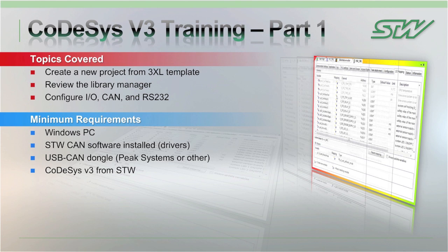So there are going to be multiple videos, and there are some assumptions that we make when we're doing this training, and that's that you're using a Windows PC and you have an STW CoDeSys version 3 installation. If you download CoDeSys from the 3S website, that will not work with our libraries. You have to install the STW CoDeSys 3 software. Also, we're using a USB to CAN dongle from Peak Systems, and we use this to link communication via CAN with our PC to our controllers.